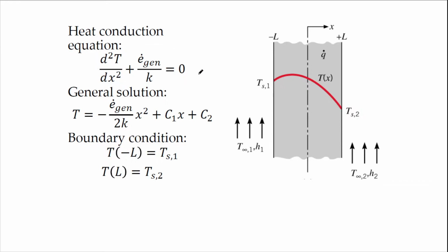With heat generation, you have this equation, and if you want to solve this, obviously you need to do the integration, and then you will have this formula. If we are working with the 1D equation in Cartesian coordinates without heat generation, this term will not exist, so what we have normally is this one. But since we have heat generation, we have additional parts over here.